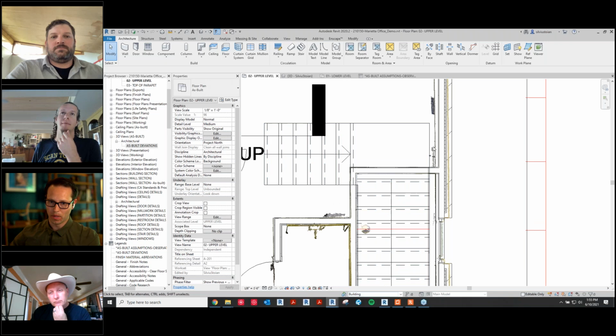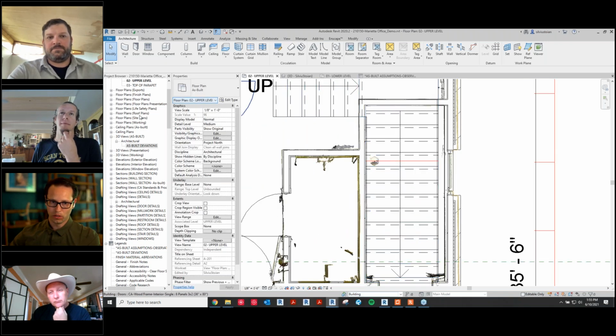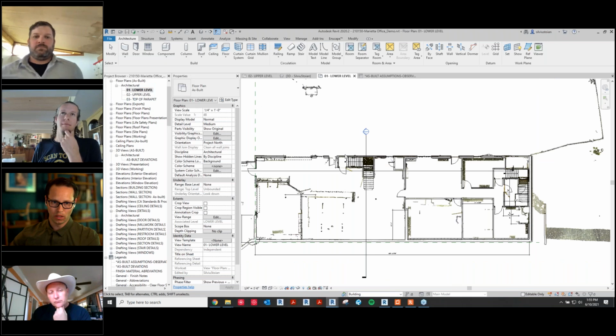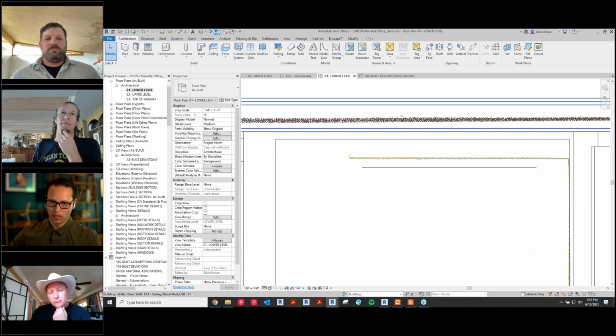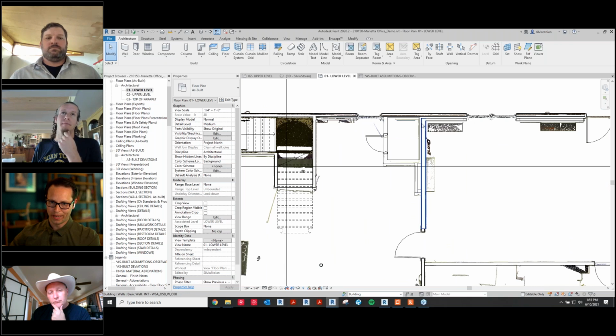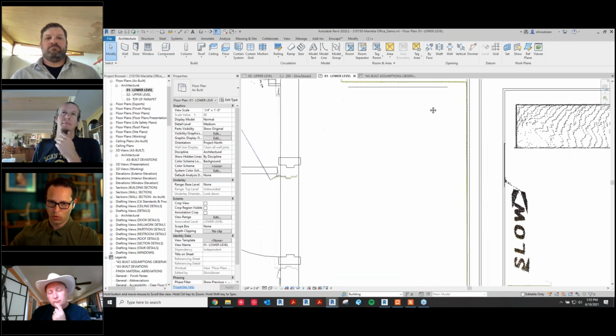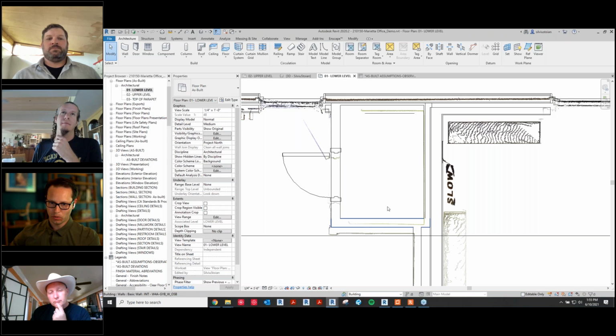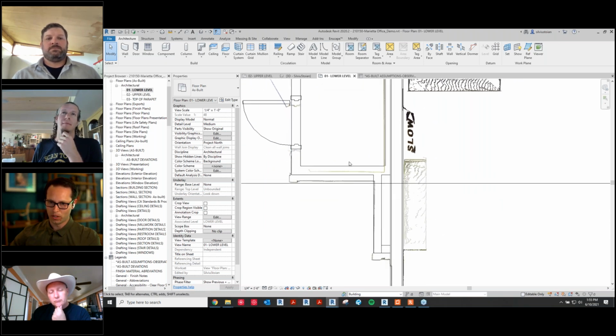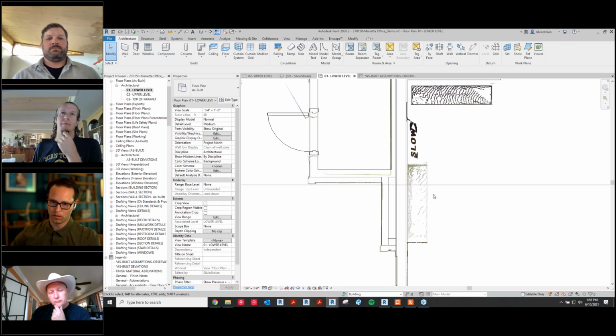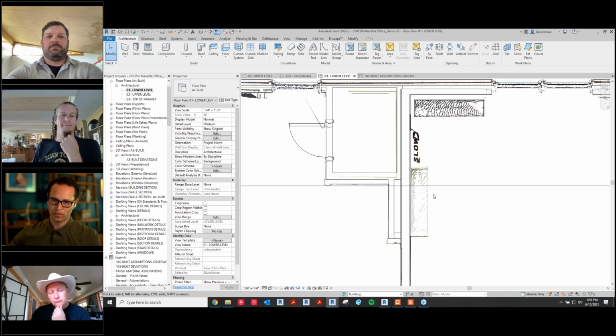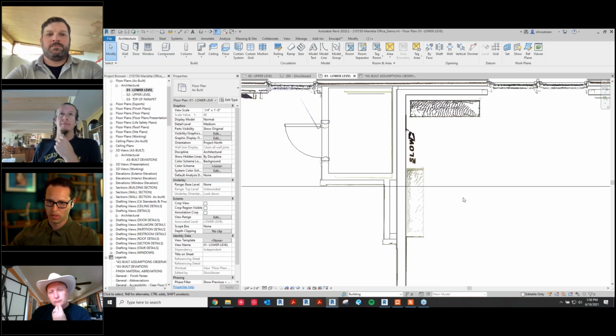So when you model any elements that are adjacent, let's go to the lower level, because this is the worst, this wall here is bowing in by about 4 inches. So when you model this small room here, make sure that this wall is relative to that one. If you're going to match the point cloud here, you already introduced error in the model, a lot of error. So all the objects have to be relative to the object around them. So it's challenging. This was probably one of the most challenging models to make sure that things were relative to each other in terms of dimensions.